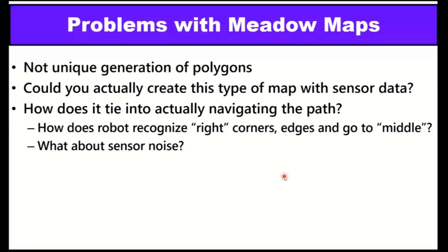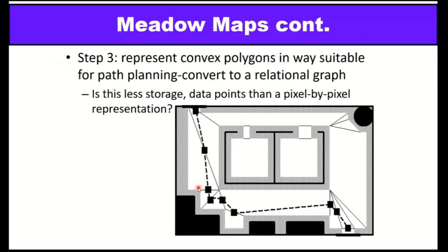The second part is sensor data. For this particular technique, we need exact sensor data. There will be another problem, that is sensor noise. What if the original sensor signal is corrupted? This problem specially occurs whenever corners are there, because you need some safety space while traveling through the corners. That's why the whole technique depends on sensor accuracy and correctness of the sensor data.